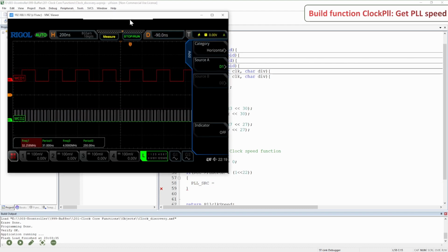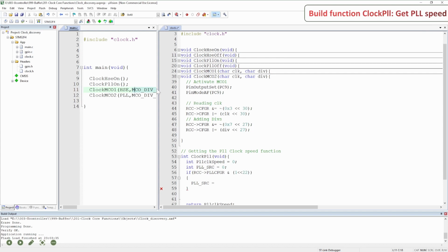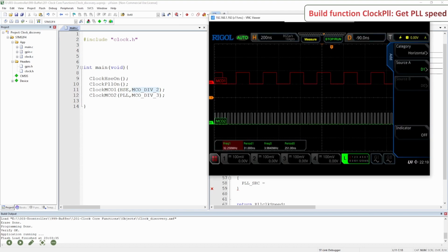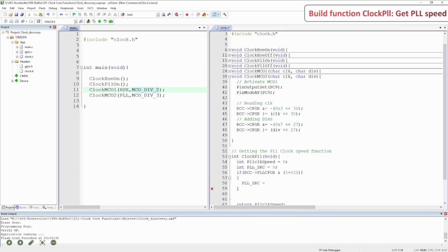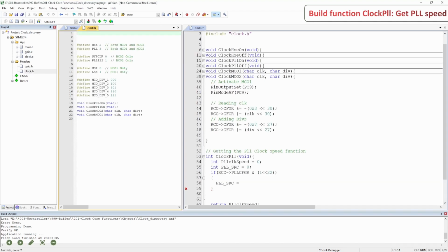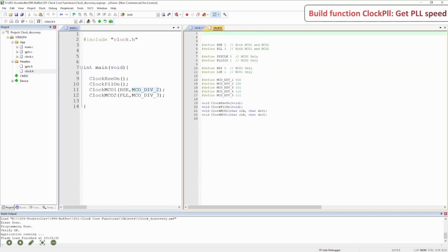So the clock here, because we had a division by 2 for the MCO1, the clock here is 8 megahertz, the external clock. And most of the standard boards that we have on the market for the STM32F4 are 8 megahertz, besides the STM32F411 as external. So let's open the clock.h here, and I prepared a certain snippet so we can have a kind of standard one.